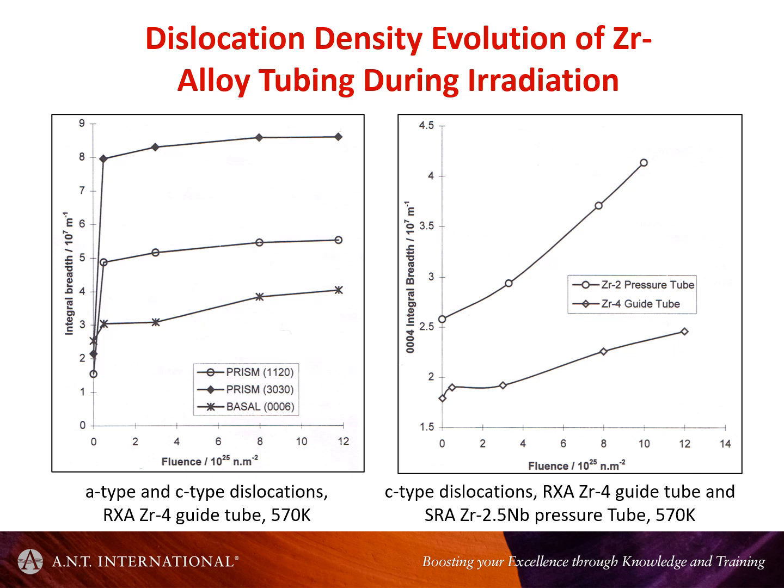The C component structure, though, there's some change in line broadening, which could be just simply residual stresses or whatever, but it takes a while before the C component structure evolves, and this point here is known as breakaway growth. So at some fluence, the conditions are right where basal loops will form, and we get this breakaway condition.